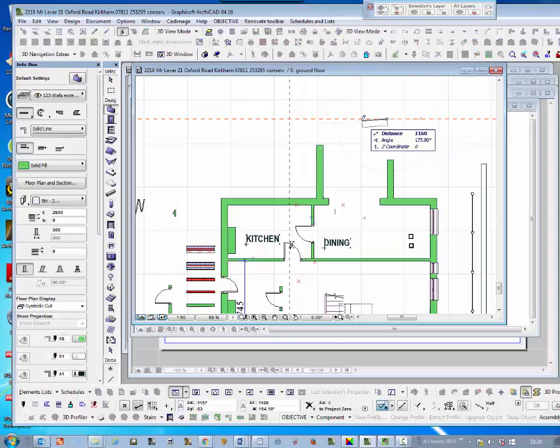Now that is starting the wall from there, but like we had it before, it's on the wrong side of the reference line. So if we press C again, it moves to the centre and then to the outside. And as you can see, it actually sticks itself, look at that, to the 90 degree point.